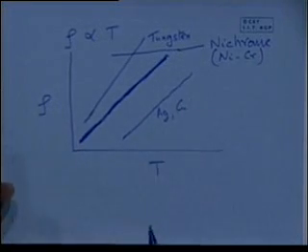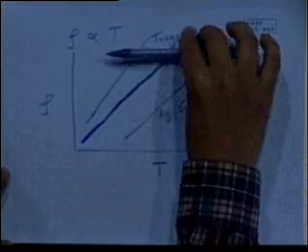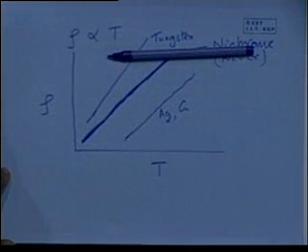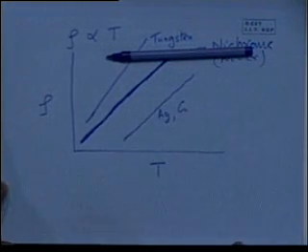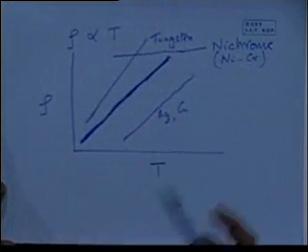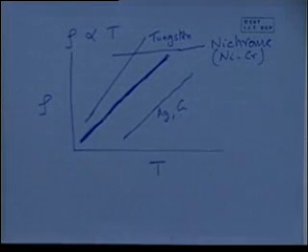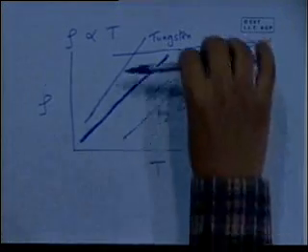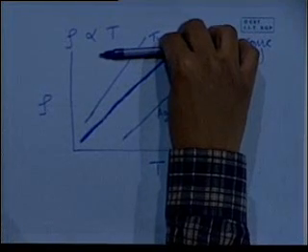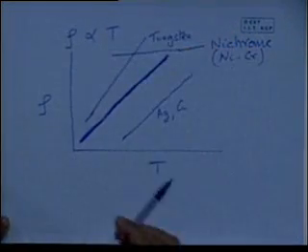You can see why. The resistance does not change much with temperature. It's got a very flat temperature coefficient of resistance, which is what you're looking for in many ways, because as you heat up the material, the amount of current it will draw will drastically change for some of these kinds of materials, and you'll have to have other kinds of electronics to control that. But with nichrome wire, you're not changing that very much, because the resistance remains relatively flat.